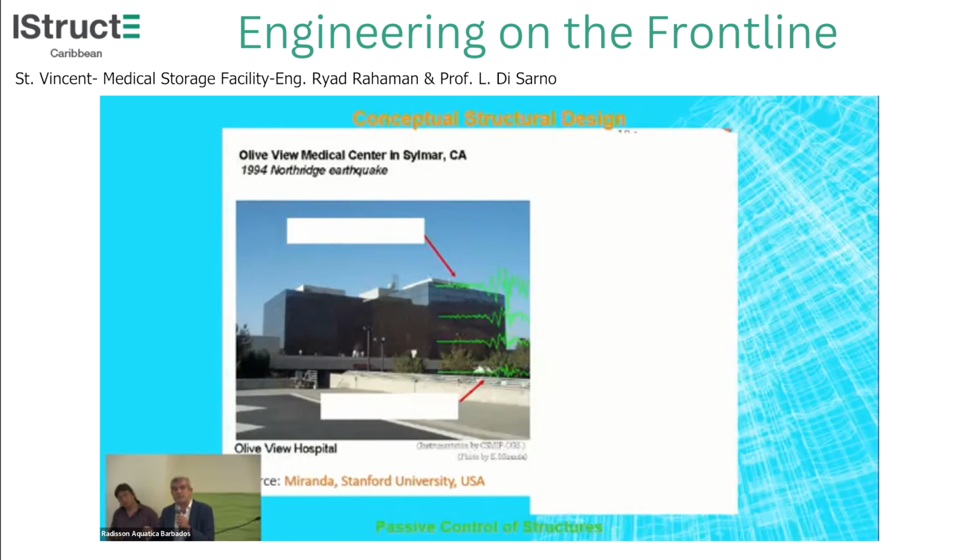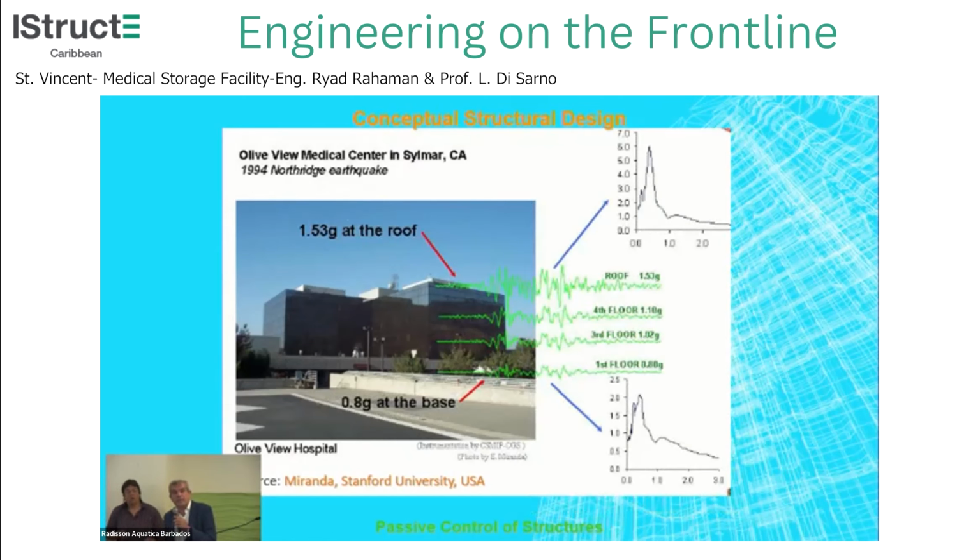Hospital. You see all these traces here that are the recording as collected during the earthquake by structural health monitoring that was along the height. So we had the possibility to follow how the building was filtering the earthquake as it was recorded. So the base one, can you go to the next one, please? Okay, so this was 0.8 at base, and it became 1.53 at the top, which means that there was an